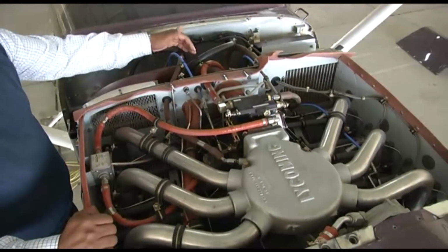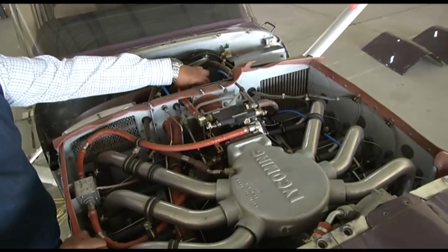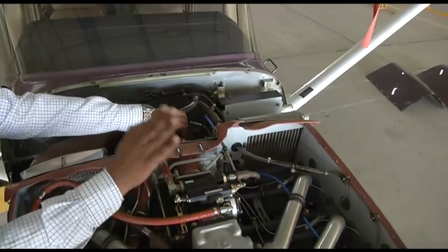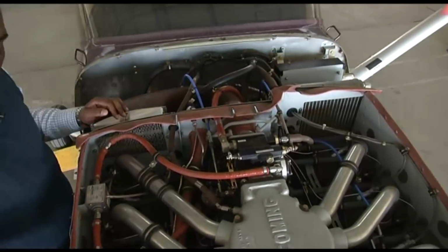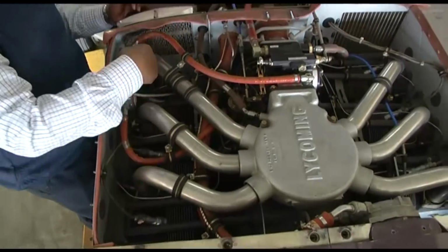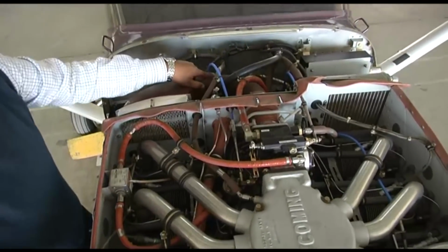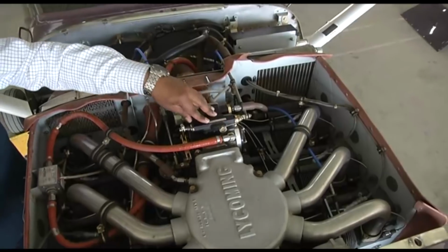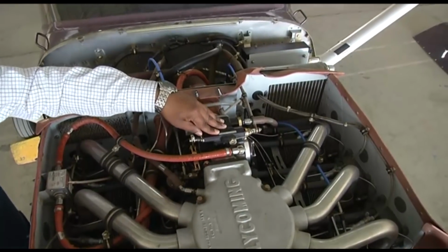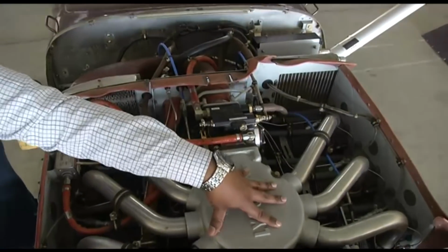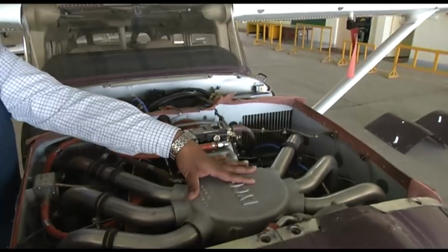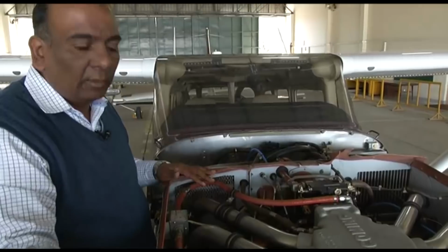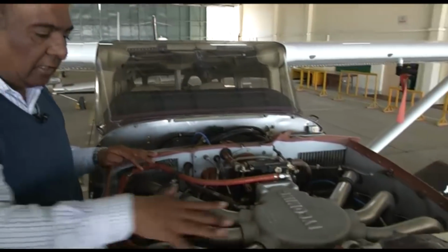You see from this side, there is a flexible duct which connects this duct to the fuel air metering unit. This is the fuel air metering unit. So the air has come from the inlet, it has gone through the filter, it is ducted through this duct and goes into the fuel air control unit. From the fuel air control unit, the air comes to the manifold. You can see this is the induction manifold, and as we have seen in our slides, there are two types of induction systems, the updraft induction system and the downdraft induction system. This is an example of a downdraft induction system.